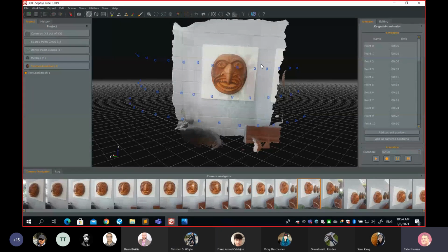So you can simply move the camera or move the object. It doesn't matter. But the problem is, don't move them at the same time. Never. Because photogrammetry will fail if you move the camera and the object at the same time. So it's either the object is still and the camera is moving, or the camera is still and the object is moving. You get the same results. Actually, from a practical point of view, people say moving the camera is better because you get uniform illumination. It has to do with the light, with the quality of your image.